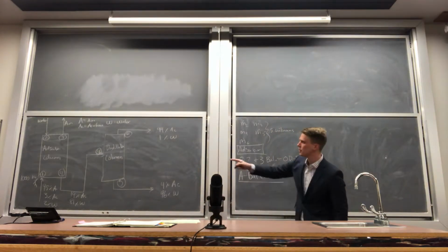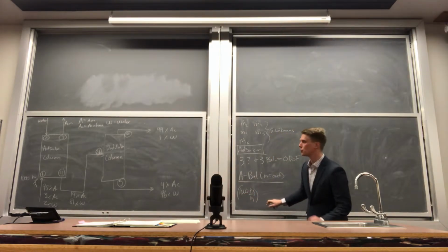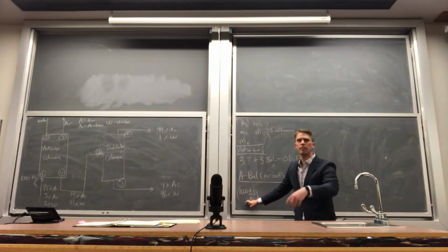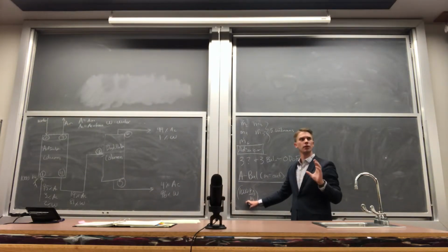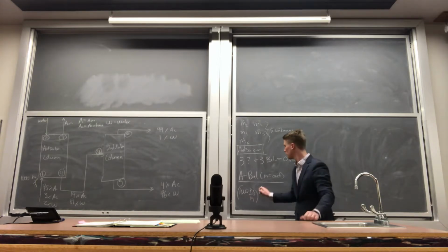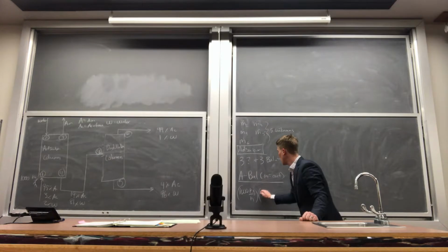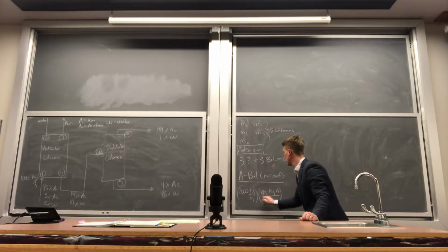So coming into the system, we have 1,000 kilograms per hour. Now the composition of this stream, because right now this is 1,000 anything: the units need to be kilograms of air per hour because we're doing an air balance. So the composition is 95 kilograms of air per, oh sorry, per 100 kilograms.